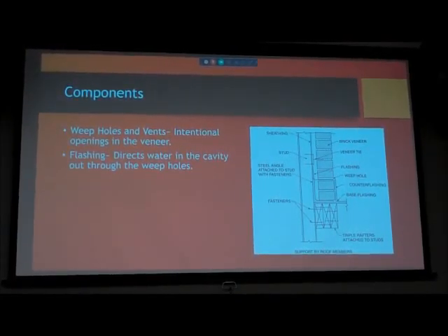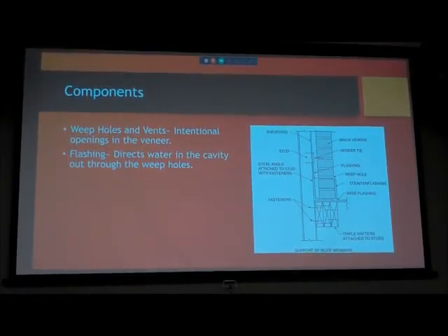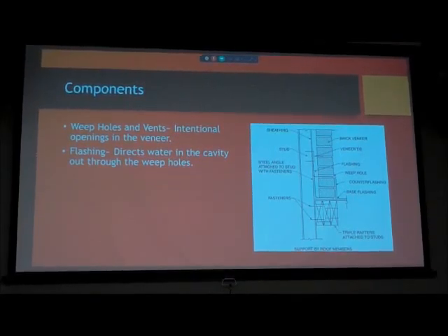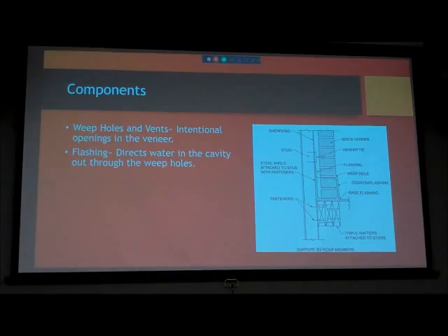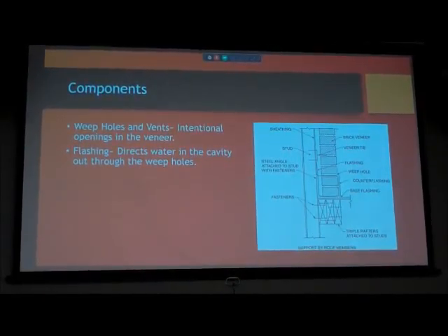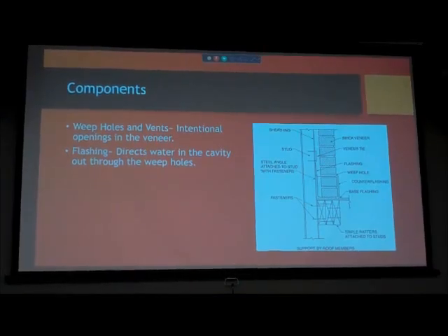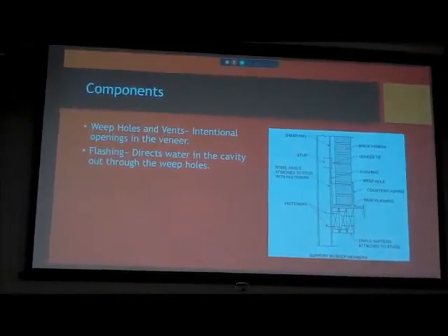They now have some plastic inserts, and you're probably going to show us some of those. They put that plastic insert in the head joint, and it's taller than the joint. It slips between the bricks, and it's porous, so it lets the moisture and air out. So there have been a lot of advances in what they use.